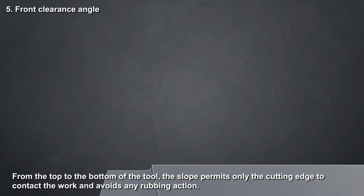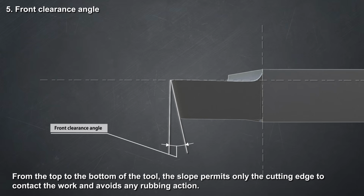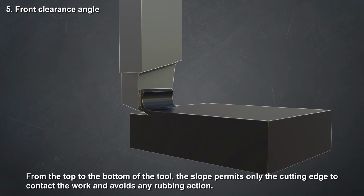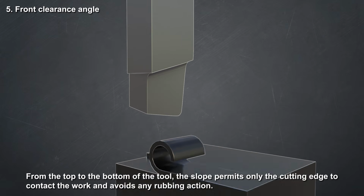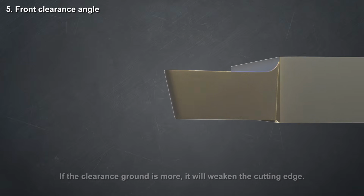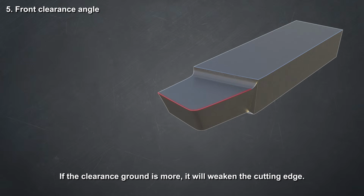Front clearance angle. It is the slope between the front of the cutting edge to a line perpendicular to the axis of the tool drawn downwards, which is known as the front clearance angle. From the top to the bottom of the tool, the slope permits only the cutting edge to contact the work and avoids any rubbing action. If the clearance ground is more, it will weaken the cutting edge.